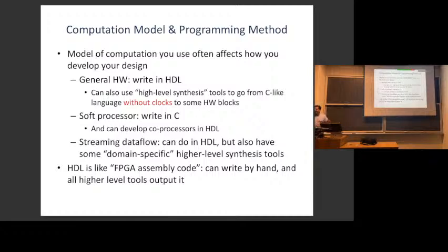And then you might go, well, but I really need some hardware acceleration working with it, so then you're writing those coprocessors, and those you write in HDL. Does that make sense? And the way you control those coprocessors is typically the processor is writing to registers, which you can do easily in C. So you're writing to specific memory addresses, which correspond to registers on your on-chip AXI bus, and all that you could do from C. Does that make sense?